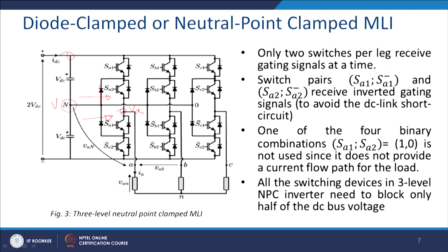I can tell you a little later that, as you have seen, this switch and this switch are complements, and this switch and this switch are complements. Ultimately, your control circuit is quite easy. Just NOT logic will work, they are not independent functions. So, what happens? You will get S2 and S1 prime. Depending on which voltage is positive, it will take the path.